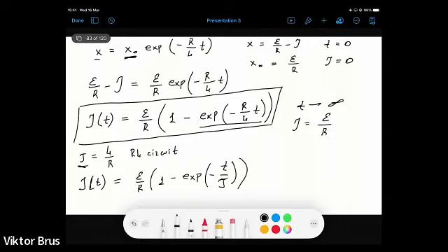So the meaning of this time constant, it just defines a time interval required for the current to increase up to, we can put it in percents, up to 63.2% of the maximum value of electric current, epsilon electromotive force divided by R. So increase from 0 to 63.2%.